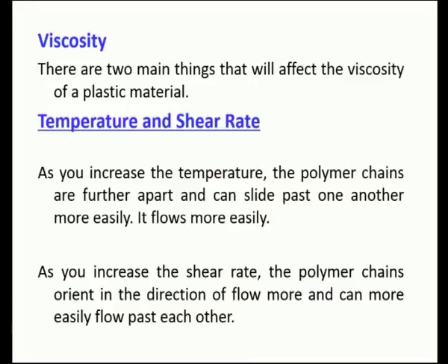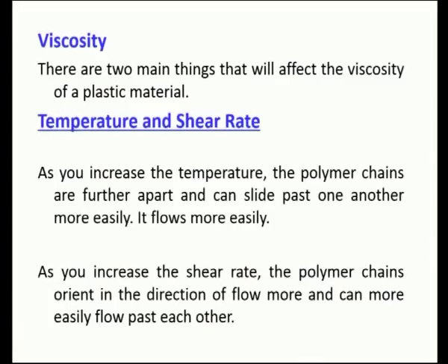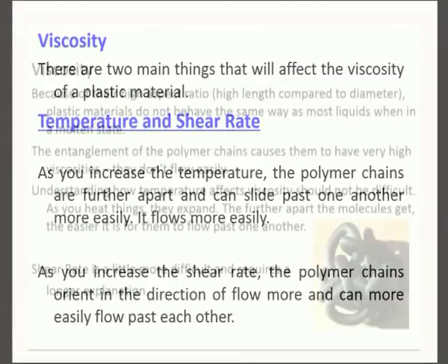As a result, the polymeric flow behavior is easier, and this is because all the entangled chains are loosened up, and then they simply slide one over the other. As a result, the flow is easier. And with respect to the shear rate, as you increase the shear rate, the polymer chains orient in the direction of flow, and again it also facilitates easier flow.